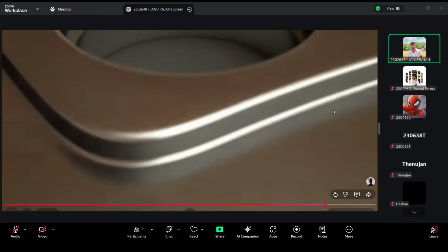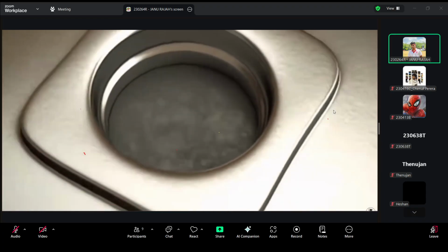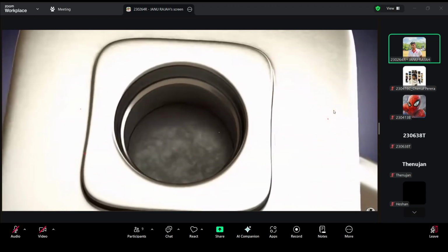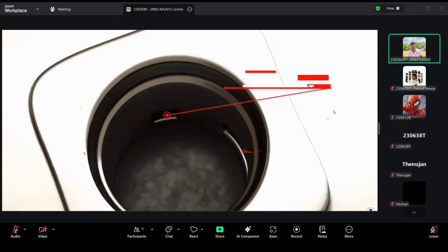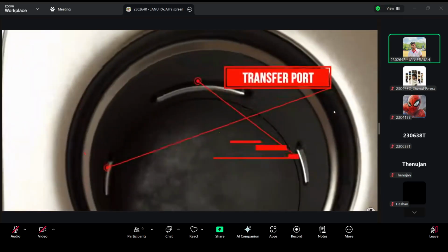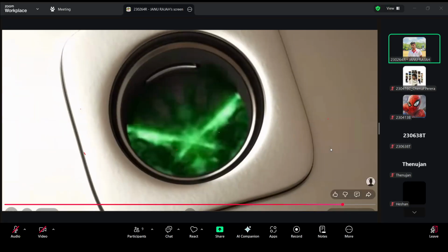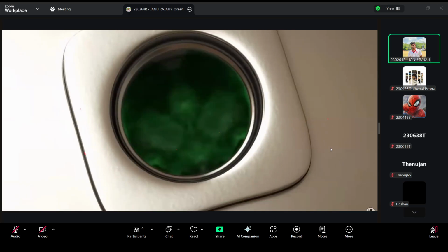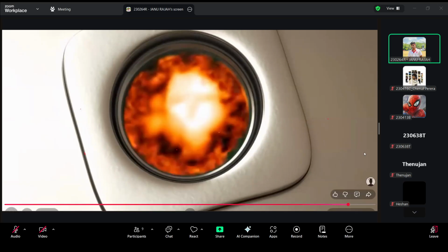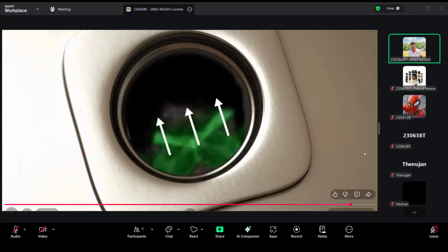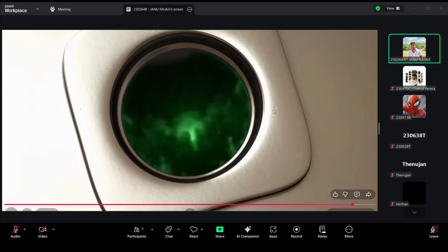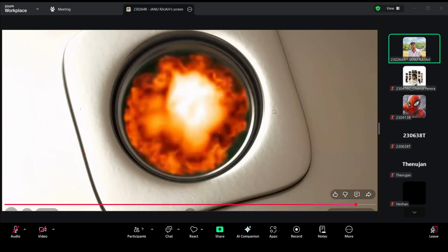The piston closes the transfer ports and exhaust port when it travels upwards. It opens them when it travels downwards. Through the transfer ports, the fresh mixture is pushed into the cylinder and filled from the rear to the front. When the spark plug finally ignites the mixture, the piston is moved downwards and fresh mixture is able to flow in. In this process, the fresh mixture pushes out the exhaust fumes.